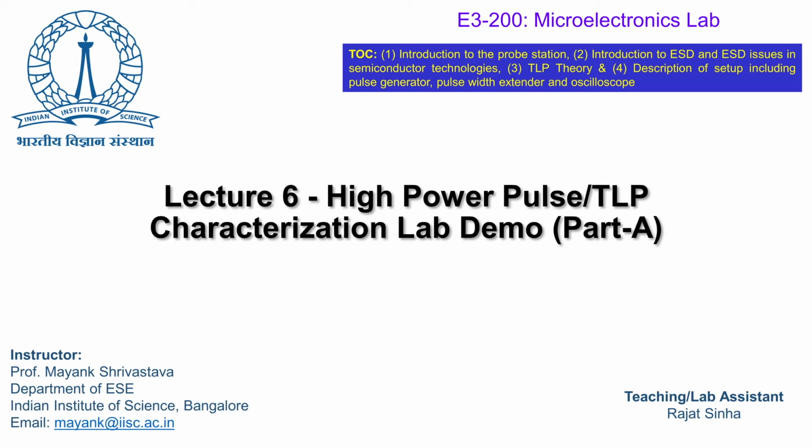We will then come to the theory of the TLP and the high power pulse setup. We will describe the setup including the pulse generator, pulse width extender, oscilloscope, the integration, calibration and all the other RF pulse measurement related issues.